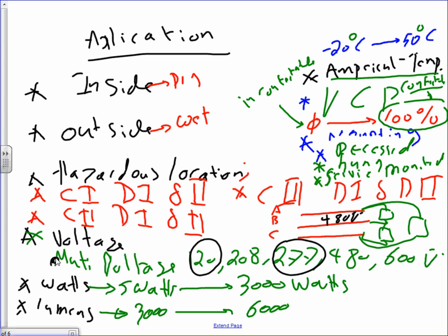Does that make sense? So please remember the VCP. I guarantee you this will be in your test too. What is the VCP? Visual comfort probability. How comfortable I feel underneath it. What does the 0 mean? Very uncomfortable. What does the 100 mean? Very comfortable. In between, typically the values are in the 70s, 80s and 90s. Can I have thumbs up, guys, about the VCP? What the VCP is? Cool.